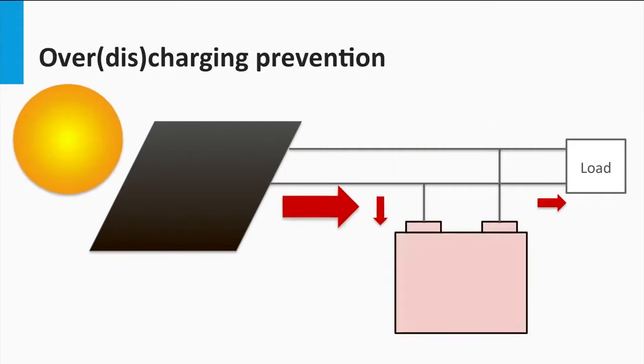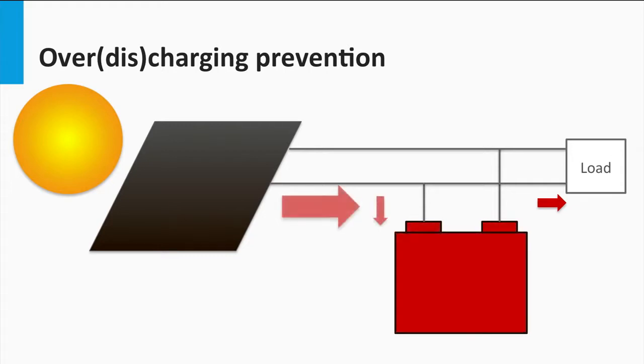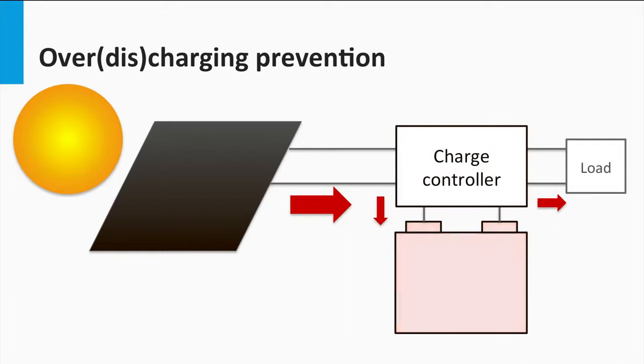When the sun is shining in peak summer, there is enough PV energy meeting the load. The excess energy is sent to the battery. But when the battery is fully charged and the PV array is still connected, the battery tends to overcharge. This brings about its own set of problems like gas formation in the lead-acid battery, capacity loss, and overheating, to name a few. The charge controller here plays a vital role by cutting off the PV power from overcharging the battery.